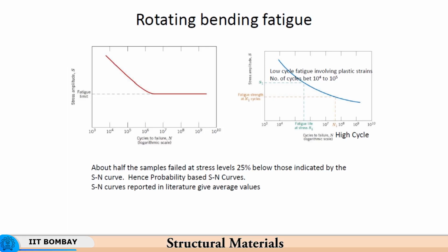when the loading changes direction from tensile to compressive, then the dislocations which got piled up being stressed in one direction suddenly experience a change in direction of loading. So, dislocations are able to move very rapidly. The dislocation movement becomes possible at a much lower stress when there is a change in direction. So, these are basically a transient phenomenon. The Bauschinger effect is a transient phenomenon that occurs when the direction of loading is changed.